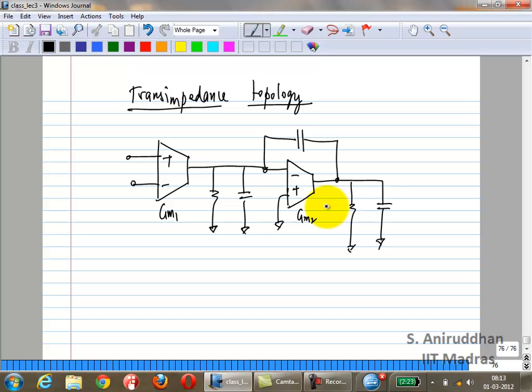Mainly because you are trying to create some transconductance multiplied by some output impedance to get the gain. If you have a resistor in parallel, the output impedance is the parallel combination of the very large output impedance you have created and this very small load resistance, and so your DC gain drops drastically. That is our fundamental problem so far, and the main motivation in moving towards a two-stage topology.